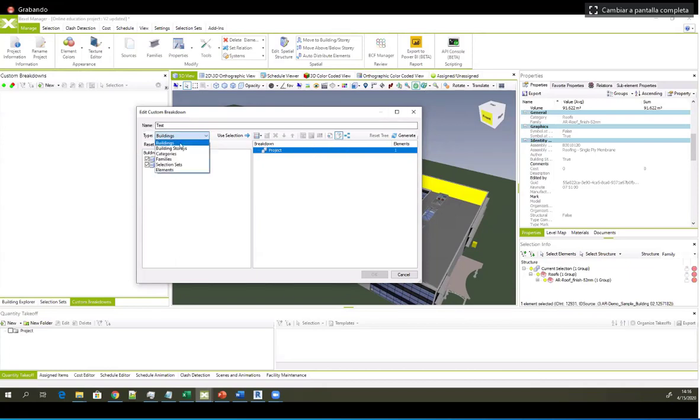The next way is just selecting specific stories. The next way is selecting the categories, available categories or the types from your B-model elements. The families are the next, let's say, level of segregation. So you can choose just to include specific types or the families coming from your authoring tool in the segregation. And the next one is using selection set or the actually selected elements.